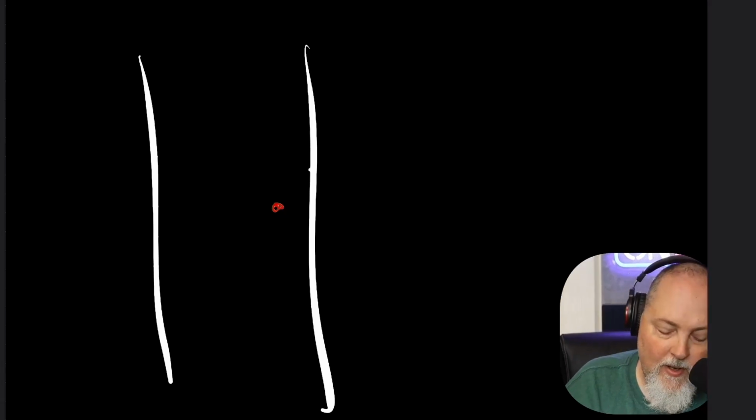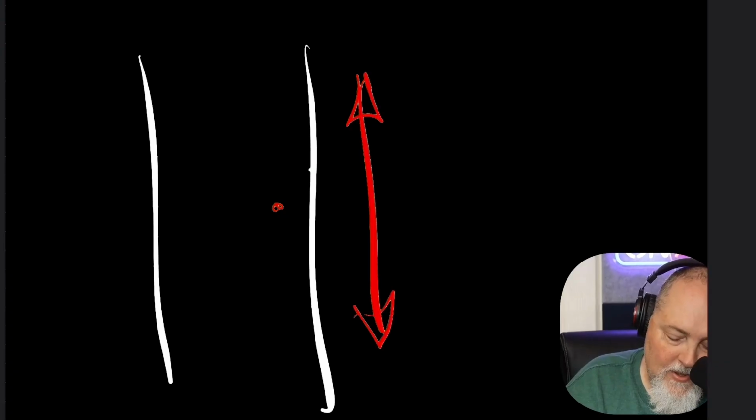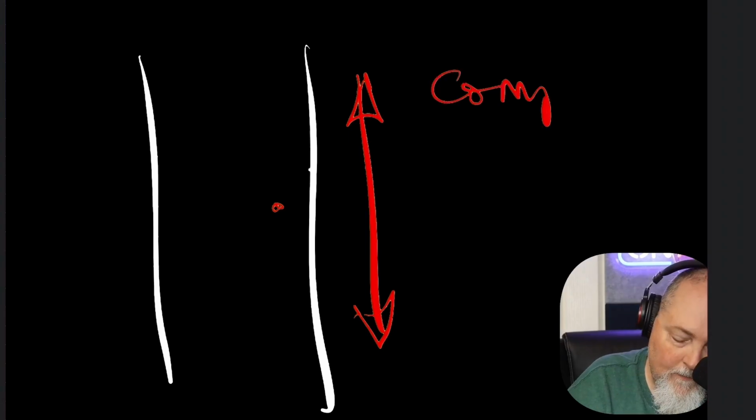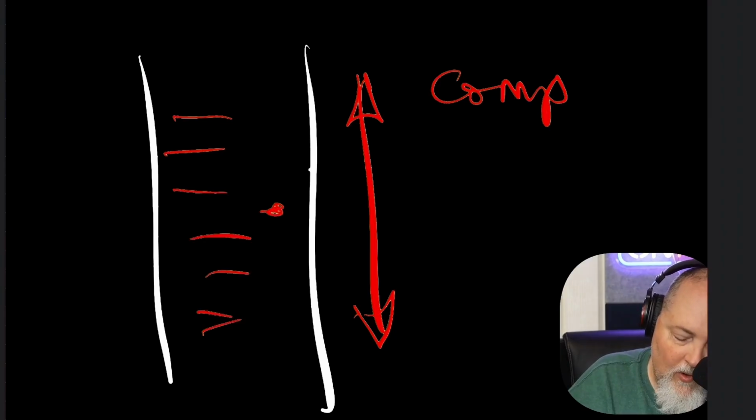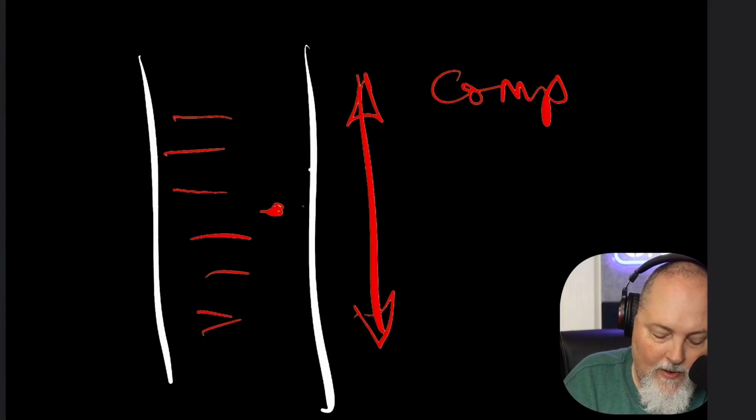All right, let's talk about stress concentrations and fracture toughness. Brittle fracture starts at a flaw or a discontinuity. There has to be something wrong in this metal. Sometimes it's near the surface, sometimes it's inside. Like if I have just a tiny little, we'll draw something red, we'll call that our flaw. Brittle fracture starts at a flaw or discontinuity. So as I have, let's say, expansion on the outside, which puts the outside surface under compression, because it's trying to expand the outside surface, and this is all tensile, this flaw is where that brittle fracture will start.